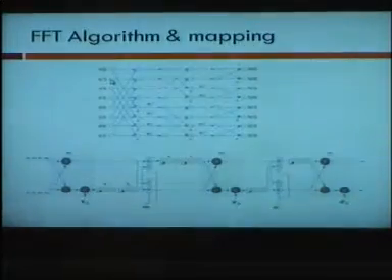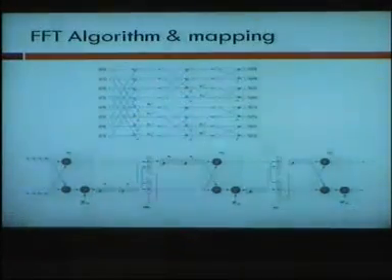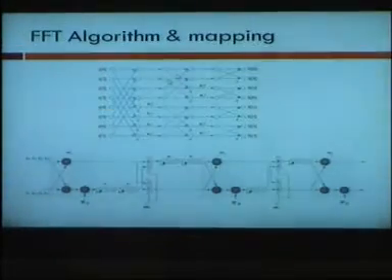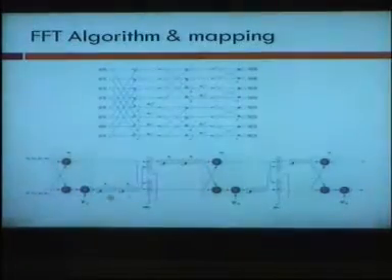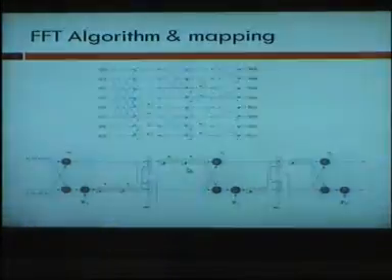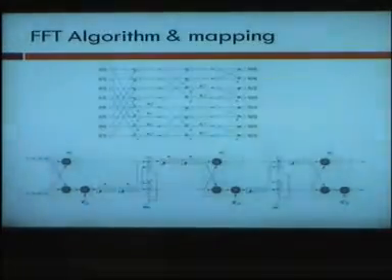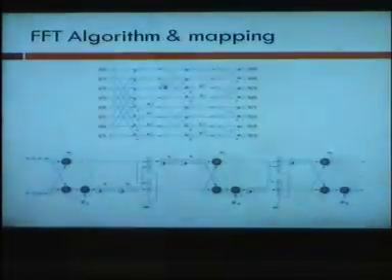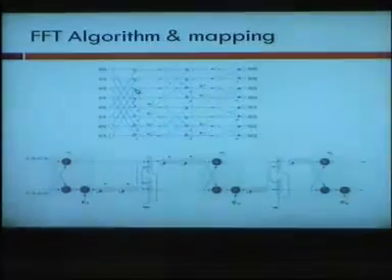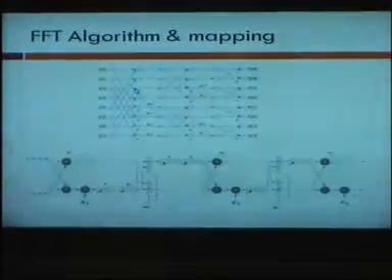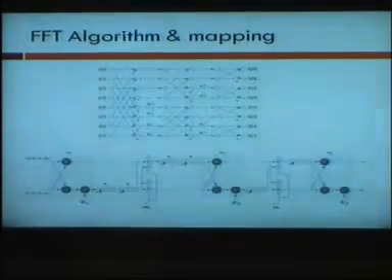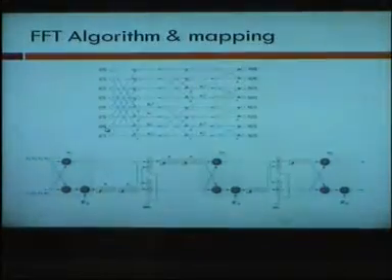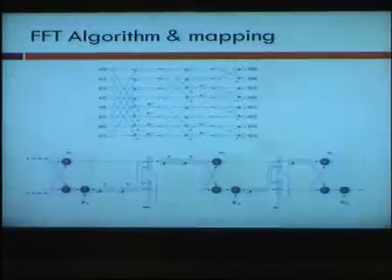data to be forwarded to a multiplier and adder in a fashion that once this butterfly gets implemented, the requisite data at the input of the butterfly is already there. So what you see here, the muxes and the registers, are placed in such a fashion that intermediate values are stored. For example, this butterfly gets implemented first, but this butterfly cannot be implemented because this input requires this butterfly, which has not yet been implemented. So it maps one, then it maps another, then another, and the intermediate structure of registers and multiplexers ensures that the right data goes to the right butterfly at the right time, so that it works in lockstep.